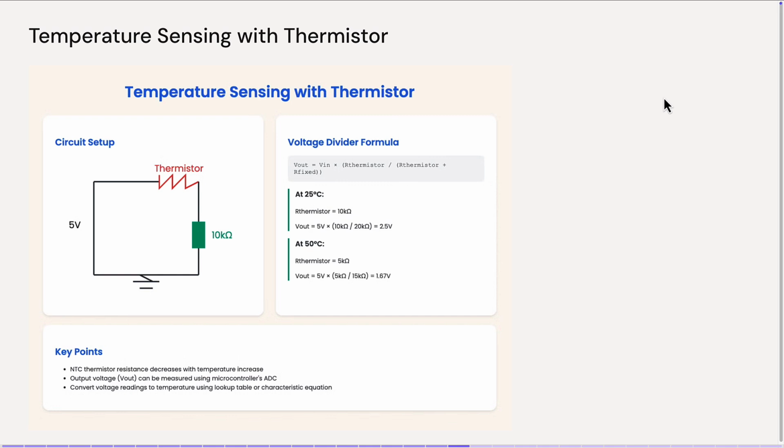Now, if you connect this to Arduino, for example, and you get a voltage of 2.5, using, of course, the value from the ADC, you can infer that the temperature is 25. So there are libraries that are going to convert this value into temperature based on the physical characteristics of this metal, which is captured by this divider, what we call the voltage divider formula.